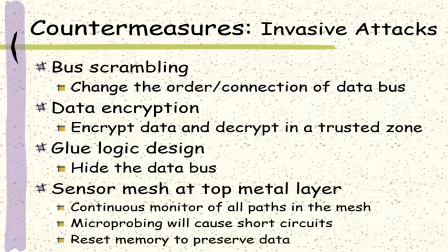To protect from invasive attacks, most of the smart cards have a sensor mesh implemented in the top metal layer. All the paths in the mesh are monitored continuously. Microprobing attempts will cause short circuits. This will trigger an alarm, and the memory contents will be reset to protect sensitive data.